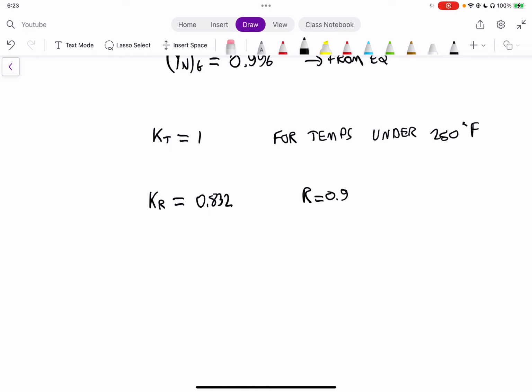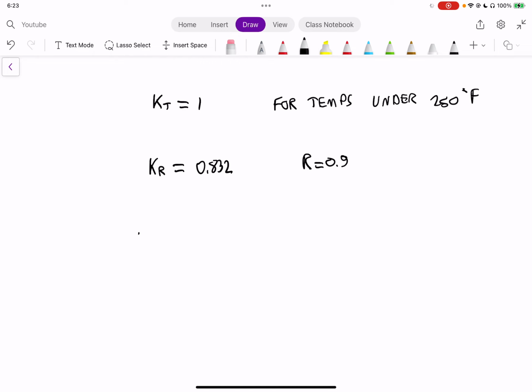So moving forward from that, we can then solve a safety factor for the pinion and a safety factor for the gear, because we have different sigmas. We have the same strengths, but we have different YNs calculated for both.